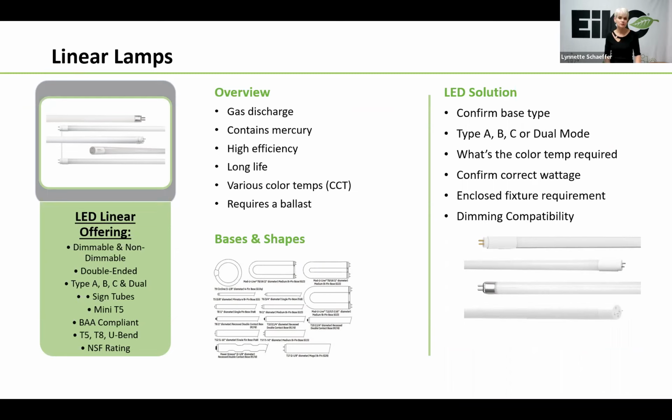When replacing fluorescent lamps with LEDs, just like the previous slide, it's important to understand if the customer wants to use the existing ballast or if they want to disconnect the ballast, and more importantly, if they want a new LED driver to be integrated into the lamp or remote mounted. Again, this is referred to as type A, B, C, and D. We'll get to more details in just a minute, I promise. It's also important to understand if the lamps will be completely enclosed. And of course, don't forget about dimming compatibility, as you've heard me say a number of times.